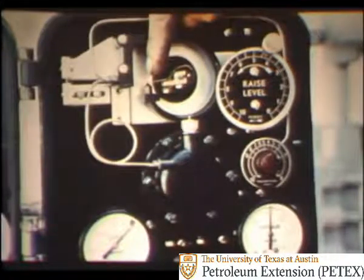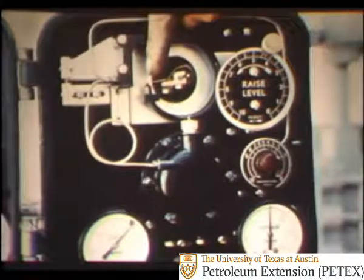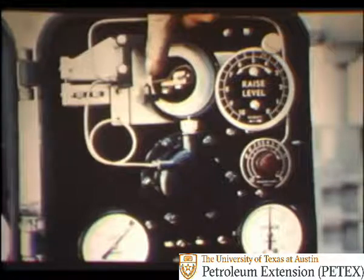Then check the controller supply air pressure gauge to be sure the controller has supply air. Confirming this, try to stroke the valve with the level controller flapper. If the controller properly opens and closes the valve, it was probably stuck in the open position. Stroke the valve several times to be sure it no longer sticks open and has a smooth action. If it does continue to stick, correct the cause of the binding. The valve stem packing may be too tight, or the valve might require lubrication.